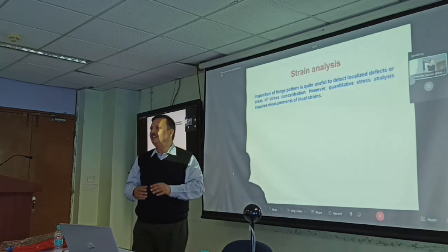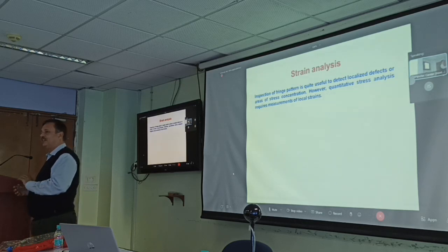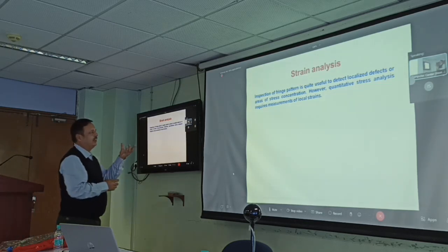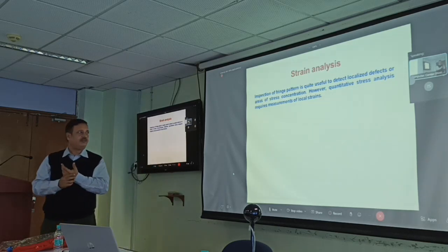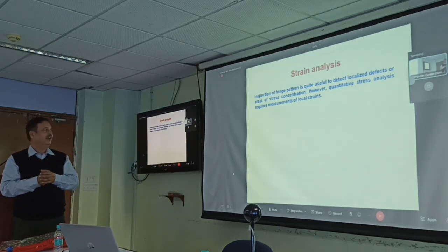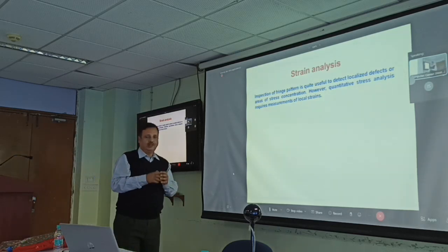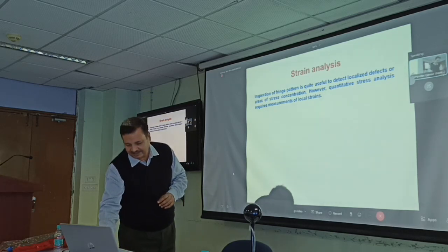Then another application is strain analysis. This is again one of the metrological applications, stress and strain. Inspection of the fringe pattern is quite useful to detect localized defects and areas of stress concentration. So how to measure this stress? How to measure this strain?